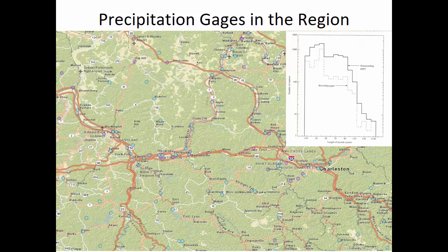You don't want it to fill up and overtop in the 100-year storm. I mean, ideally for a dam, what they're designing for is maybe the 10,000-year storm or the 100,000-year storm. They're really planning on the worst case scenario and they want it to hold up no matter what. Not every structure has to be built to that same standard.